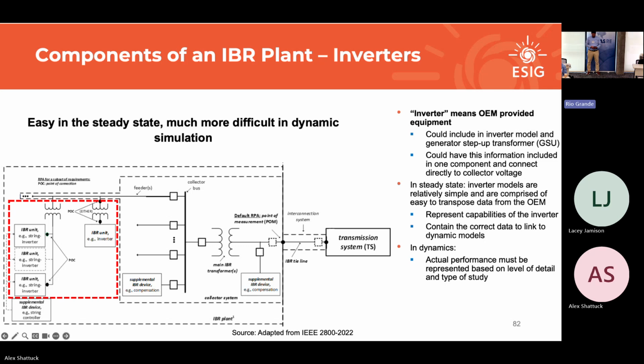One may have an actual step-up transformer in there. In the EMT world, it may be more of a scaling transformer where you'll have a number of inverters in one representation of the inverter, and then you can select a number of inverters in the transformer, and that'll scale the transformer up and do the calculations for you to equivalentize X number of transformers in your configuration. So there's different ways that you'll get these models from folks.